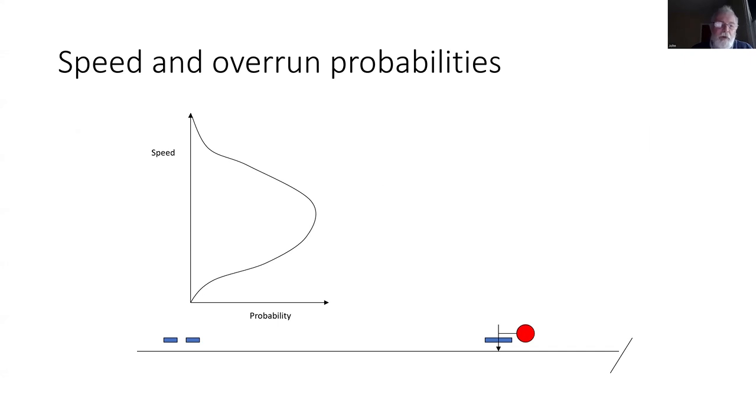And if we look at the location of the OSS, then looking at historic data, we could see that the speed the train would pass the OSS position was a roughly normal curve, with a probability of the train going very slowly being small, most trains travelling at around about the 5 or 6% braking curve to the red signal, drivers having reacted early, a few trains going a little bit faster, and just a few trains going fast enough to exceed the OSS set speed. Or in this case, they also need to consider that a few would exceed line speed.